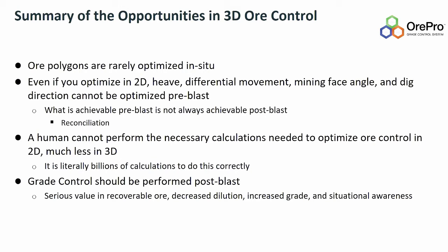One, the essentially selective mining unit that you want to use. What is the minimum polygon width and the minimum polygon length in the travel direction of the equipment? Okay. If you're going to use, let's say, backhoes and sit on the pile and excavate, then you can assume a 90-degree face if you're doing really short flitches. So that mining face angle is a consideration.